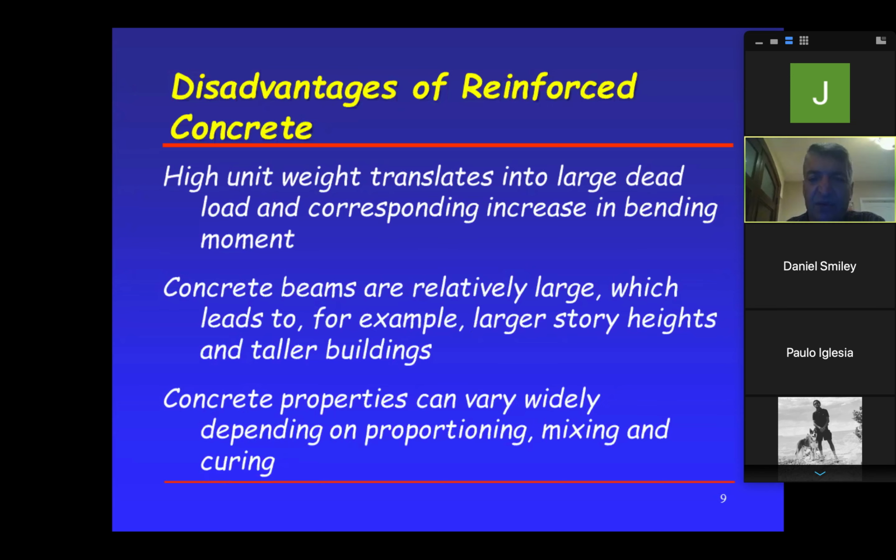All right, so that's another one. So curing, very important. Sometimes on the freeways, instead of dumping water on it all the time, they go ahead and cover it with very thick fabrics, and they keep that fabric wet because the fabric would keep the moisture down versus if you just spray it on the top. Okay, so there's a lot of ways to do it.